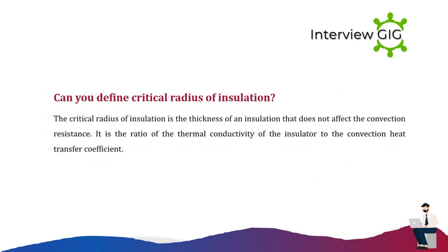Can you define critical radius of insulation? The critical radius of insulation is the thickness of an insulation that does not affect the convection resistance. It is the ratio of the thermal conductivity of the insulator to the convection heat transfer coefficient.